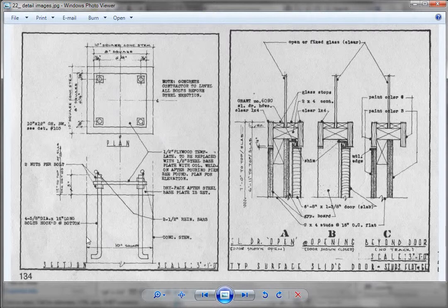You can see it here. And then the plate itself is 8 inches square. Now if a 4 by 4 goes in here, then you subtract 2 inches from 5 inches and you get a 3-inch offset, right? So the edge of the slab, the column's going to be 3 inches offset based on this. So we're just going to go with that for this particular exercise.